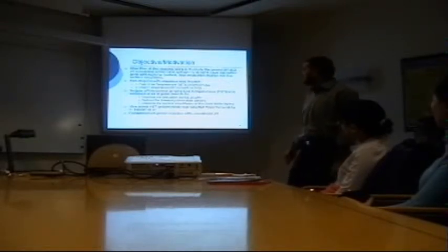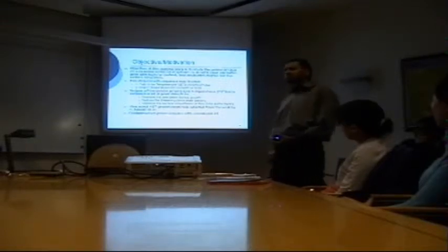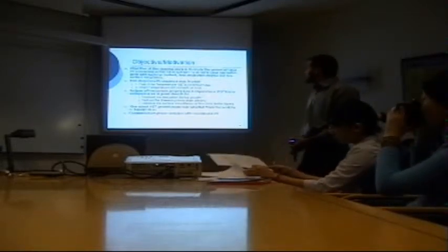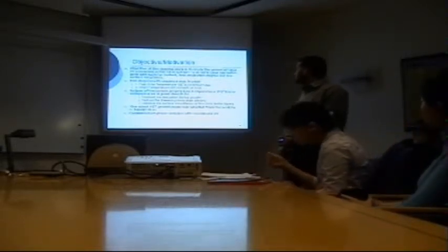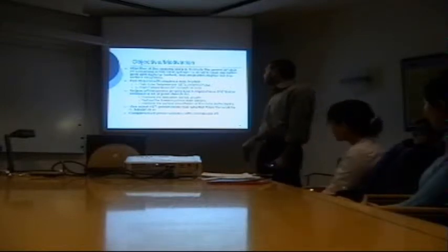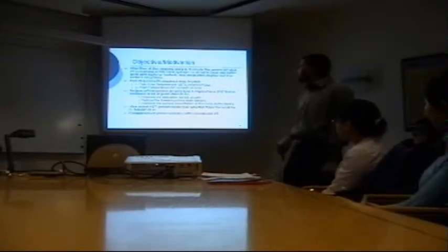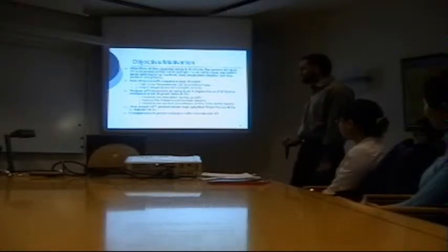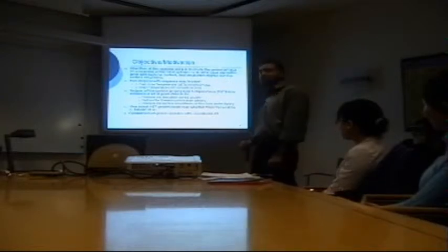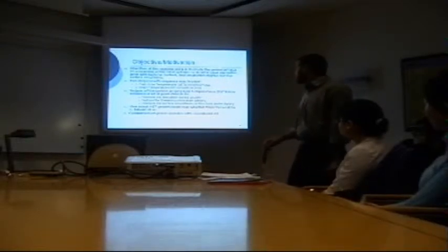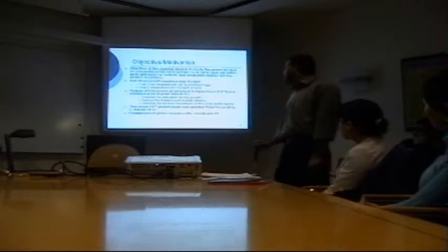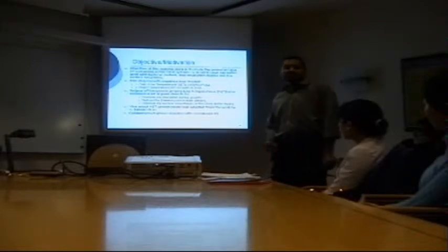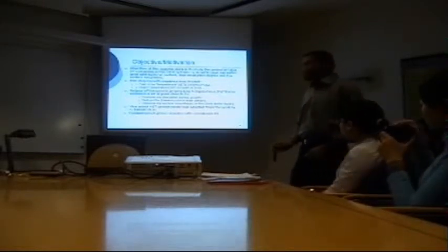And the purpose of this very low temperature growth step is to introduce a lot of point defects. So these point defects can help to promote the relaxation during growth. They can reduce the threading dislocation density, and they can improve the surface smoothness of thin silicon germanium buffer layers. The idea of having this very low temperature growth step was adopted from the work by E. Kasper. And then finally, we compare our grown virtual substrate with a commercial virtual substrate to check their quality.